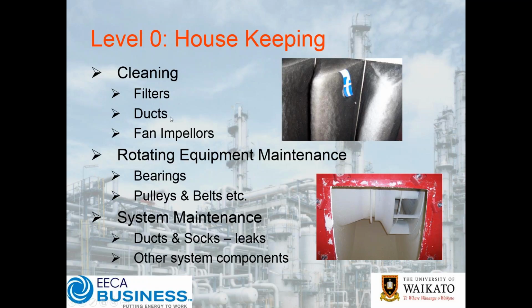Ductwork, have we got material building up in our ducts that becomes a problem in terms of blockages? Have we got material building up on impellers? There's not just an energy impact there. It might also be a safety issue, where an imbalance problem might come into the mix and you could potentially do some serious damage to your equipment. So it's understanding the degree of cleanliness that you need in your system.